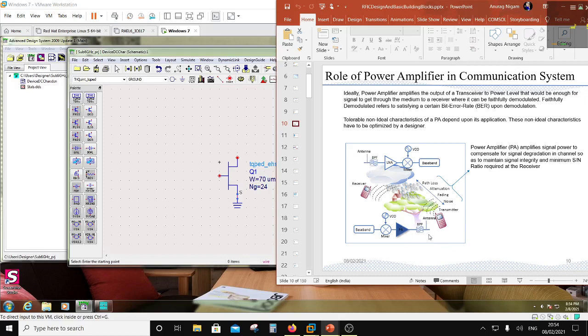So between the antenna and the PA and LNA, there is another thing which may be what you call a circulator or a switch. Now, why is that there? Because if we have a common antenna to transmit and receive, so let's say there is one terminal which transmits and receives, the other terminal also has a transmitter and receiver, right? So we need some mechanism to share the same antenna for transmitting and receiving. Now, in case transmit and receive take place at the same time, that is in the same time slot, then what's going to happen? There is going to be a frequency selective network which will isolate the two paths. So basically you will be transmitting in one frequency and receiving in another frequency, and this antenna sharing is done using a circulator, right?